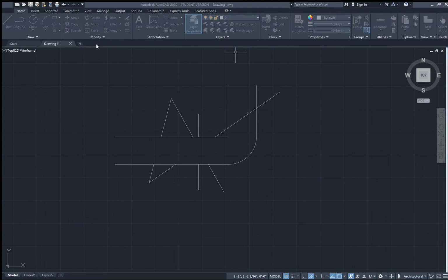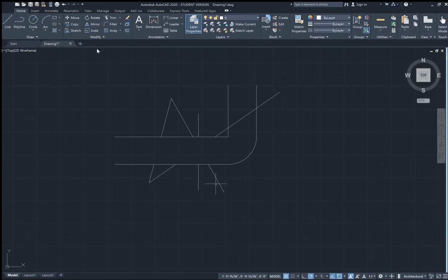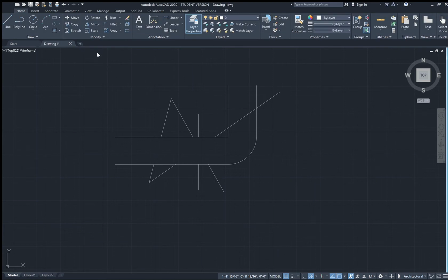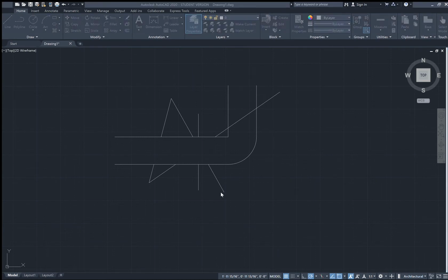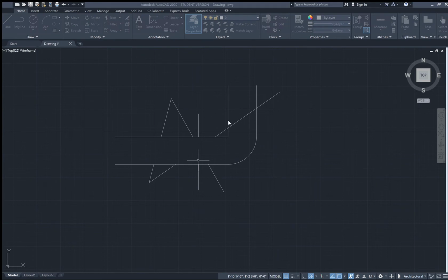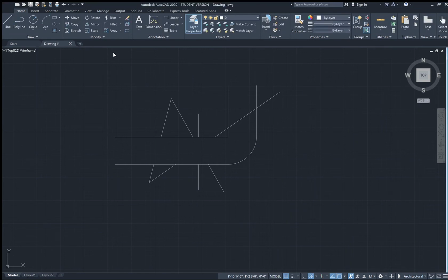You're able to choose the color first that it appears as. So for apples, we'll select red. For bananas, we'll select yellow. And for cantaloupe, we'll select green. There we go. And with these types of lines, if you've ever looked at an architectural drawing, you know that not all of the lines quite exactly look the same. So, for example, line weight here, we can choose for each of these layers to have specific line weights, how heavy they look in the document. So for cantaloupe, let's just select 1 millimeter, a really thick line.